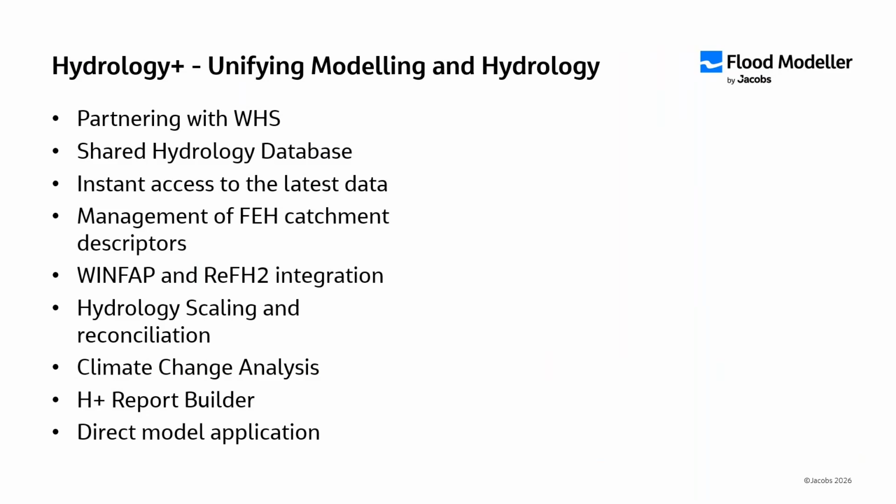We've introduced a hydrological database allowing you to store all your hydrological data within Flood Modeler and giving you instant access to the latest data. And I'm going to show you all this in just a second. You can manage your catchment descriptors within Flood Modeler. We've integrated the software, and we've got the full hydrological workflow from data collection through WinFAP and RFH analysis, hydrograph scaling and reconciliation, climate change analysis, and at the end of the day, automated report building, which we're continuing to improve, as well as direct application to the model. So what does this look like?